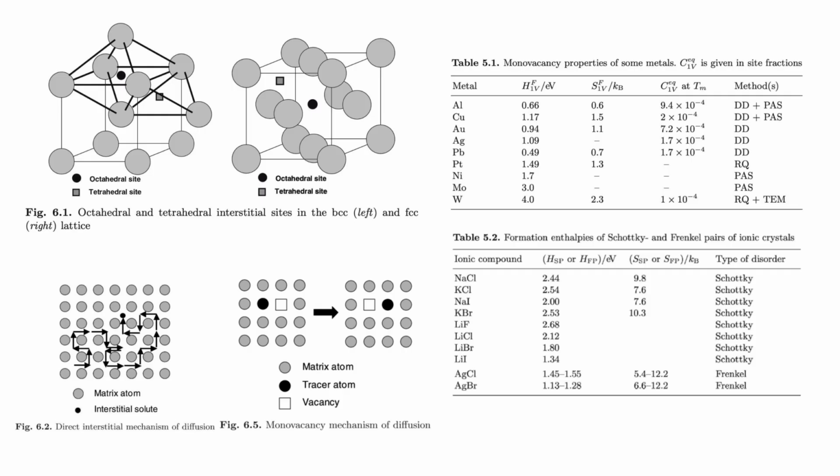But something we didn't talk about is how hard is it to create a vacancy? Because we sort of touched upon how hard it is to create an interstitial site. Last time I think I gave you two numbers. If you put the carbon in the octahedral site versus the tetrahedral site, the energy is lower by 1.5 eV, so that's a lot. But how much energy does it take to create a vacant site, like shown here? Let's say we have iron here. Why does it prefer a vacancy?